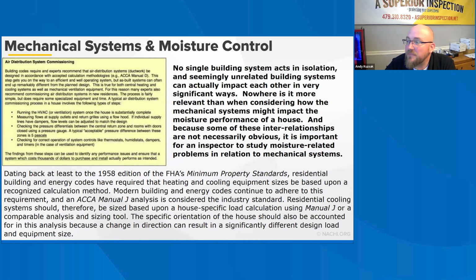served by the system. The measurement CFM 25 denotes the air leakage from the duct system measured at a duct pressure of 25 pascals. Actual testing of the duct system with a duct blaster test can be conducted by home energy raters or utilities. Suitable sealing materials include UL 181 rated foil tape and mastic.